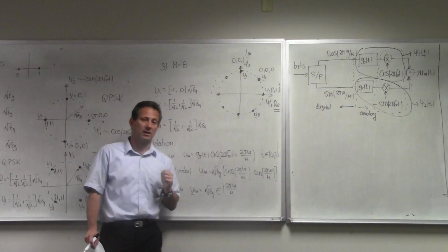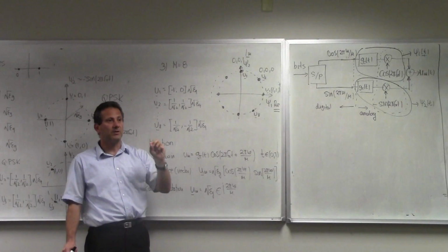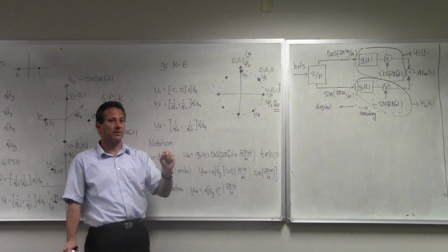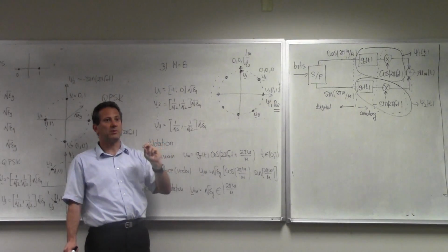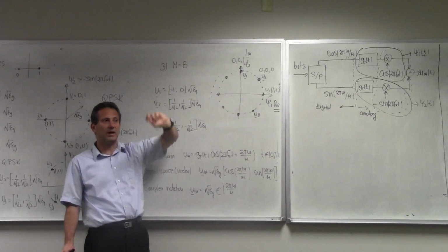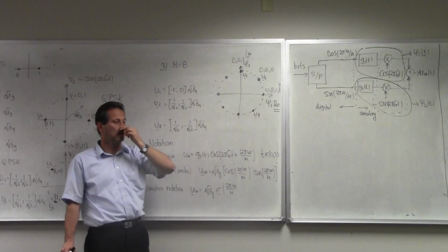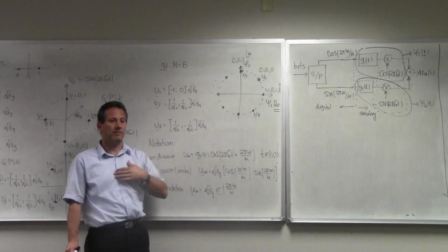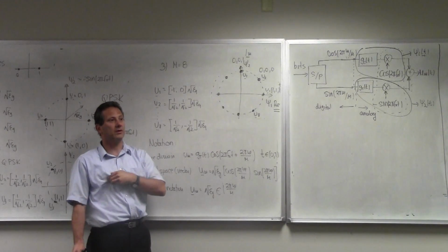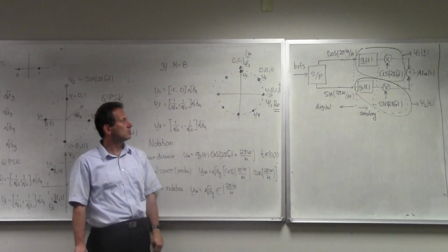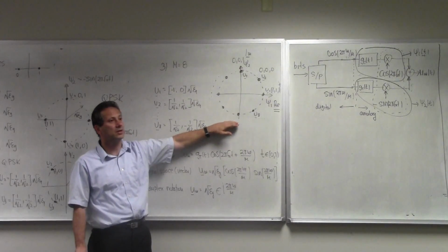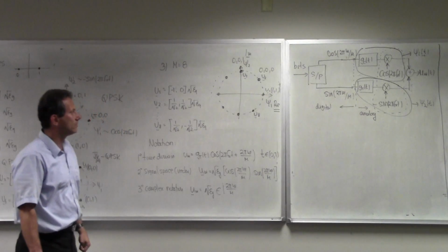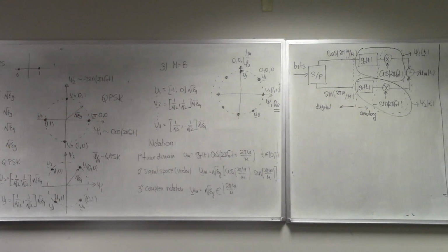This is a precious property when you try to amplify these signals. What happens is, if you maintain constant power, then you can use cheaper amplifiers because you're not going through a wide range of powers, and you can have amplifiers that are not very, very linear, right? So this is from the standpoint of electronics. This is a cherished property, that the signal remains of constant envelope, constant power.